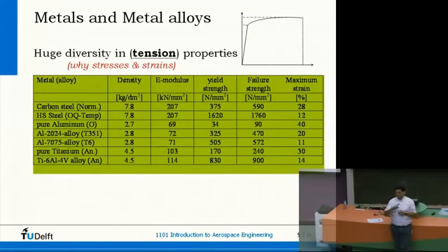Well, if you calculate it for tension, you actually get the stress divided by its density. And that's what we call specific stress. Specific strength, specific yield stress, and so on. Realize this is also only for tension. If you go, for instance, to bending, or if you go to compression, you can have different ratios, different formulas for the stress and the density.